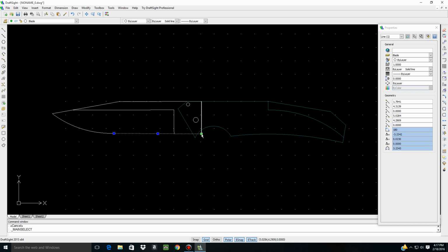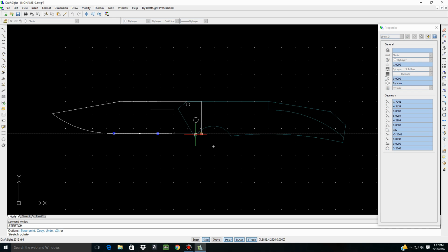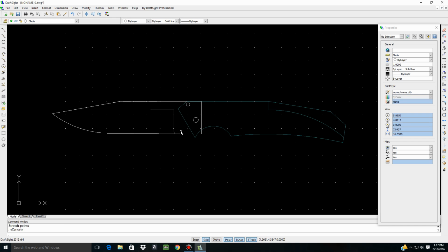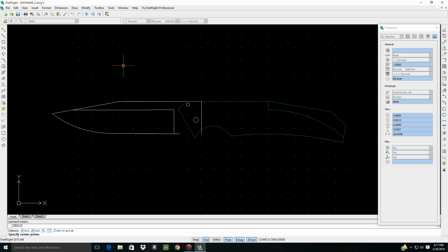So, we're going to take this line, and we're going to drag it and drop it right about there, right past the grind. Now, you could even go back a little bit more, but let's create a flipper tab. Go back to the whole principle of think of what tools you have and what you can do to create this. So, for me, I have a small wheel attachment. I can probably do a 3/4 inch wheel and get a nice radius here on the flipper tab.